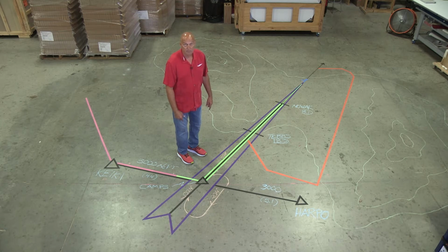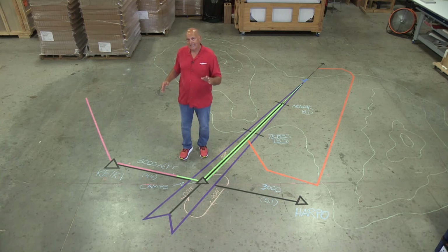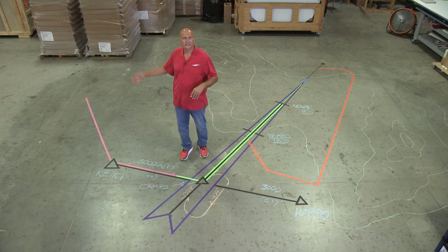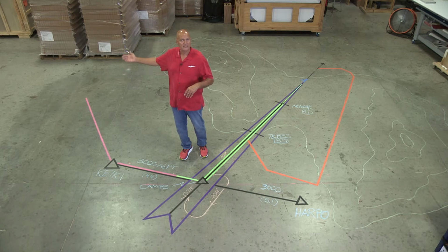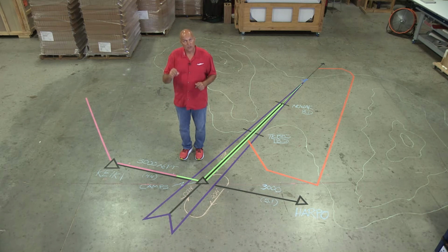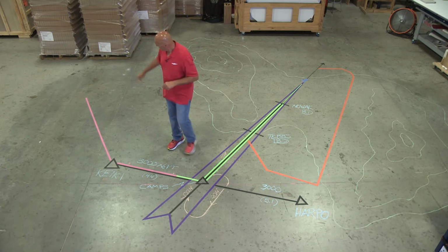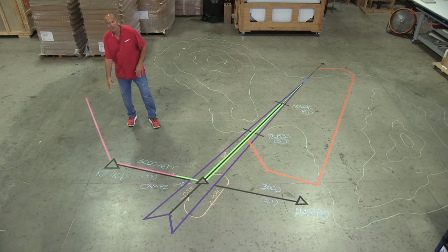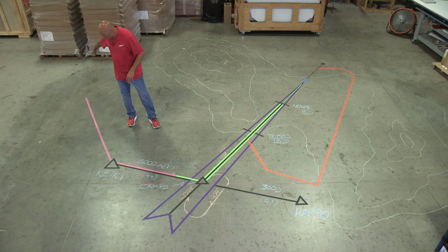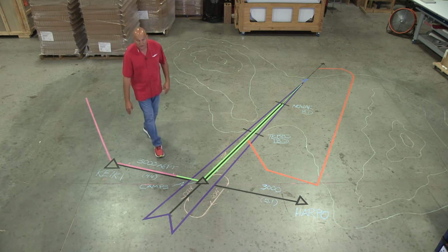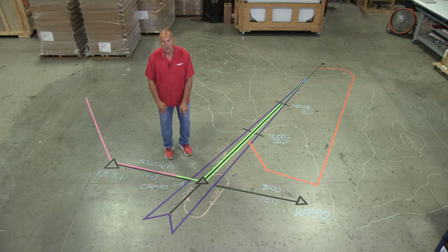So let's say that I ask the students, okay, you're somewhere over here northwest of the island. Let's say you're coming in from Molokai or perhaps Lanai, and you're going to set your approach up in, let's say, a G1000. If you start that approach with the G1000, you can start with your GPS as well, which is noted by this magenta tape on the floor. So you can start your GPS coming in into Keiki. And then from Keiki, you can also turn your GPS to make your turn toward camps.